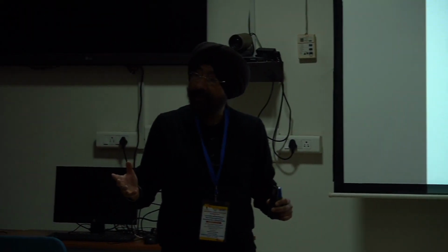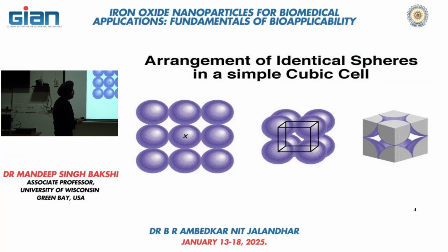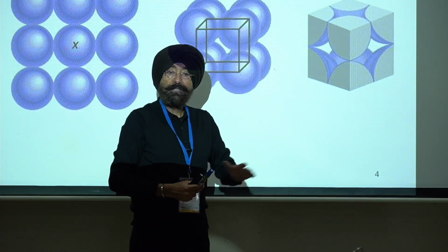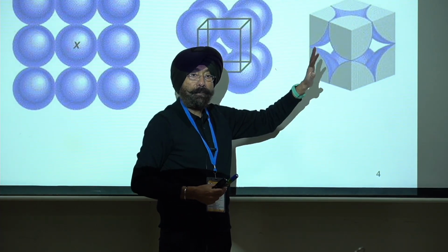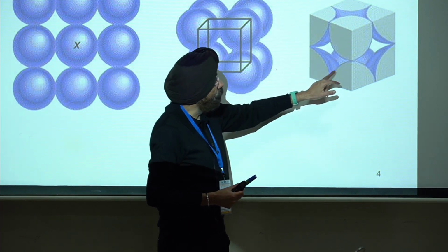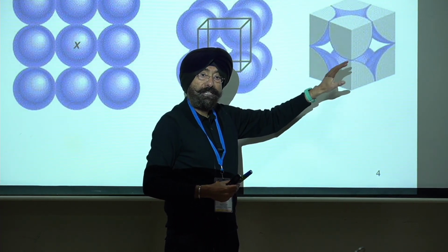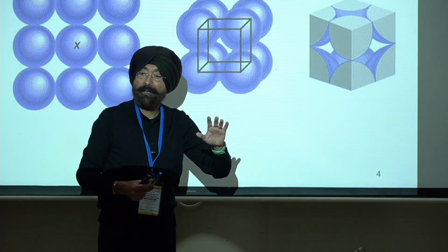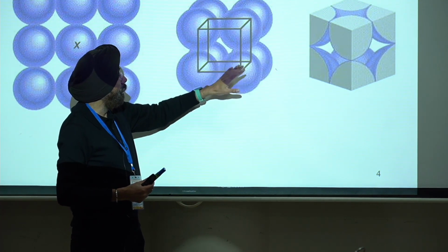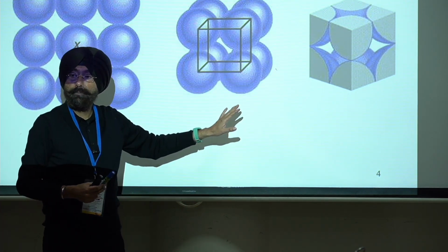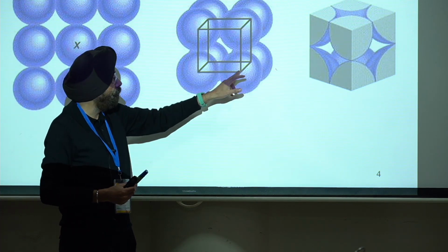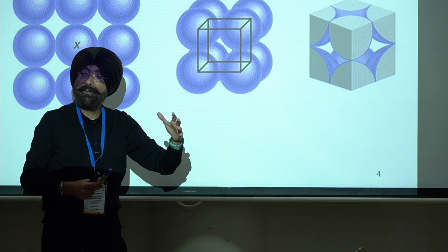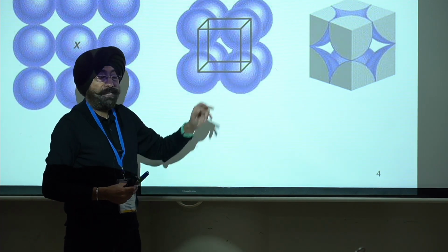Now, what is the meaning of this? We are trying to understand that. This is in fact the unit cell, right? The unit cell is the one that is repeating. So this is the unit cell which repeats itself in 3 dimensions. Anything outside the unit cell we are not considering for the time being. As you could see, we have drawn the cube, the unit cell, by taking the center of each atom. Therefore, a greater amount of each atom resides outside the frame.